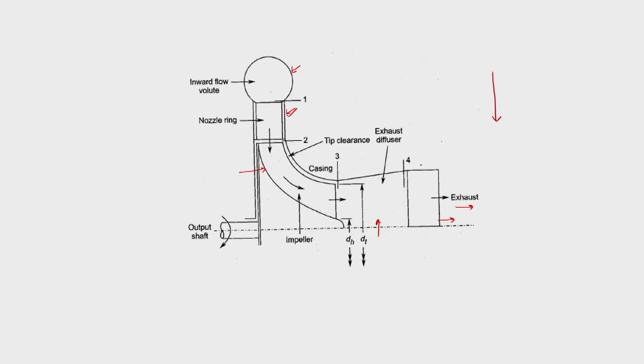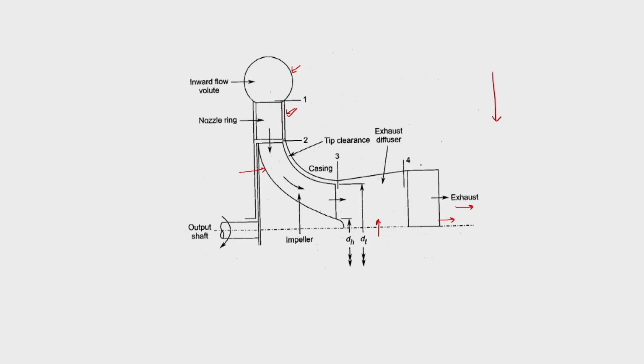As we have seen, the axial flow turbine is very compatible and generally preferred for aircraft since it has lesser drag for a given diameter. But as we go for higher pressure ratios, the diameter needs to be increased for the axial flow compressor or axial flow turbine, so their drags are higher and these machines are not generally preferred.